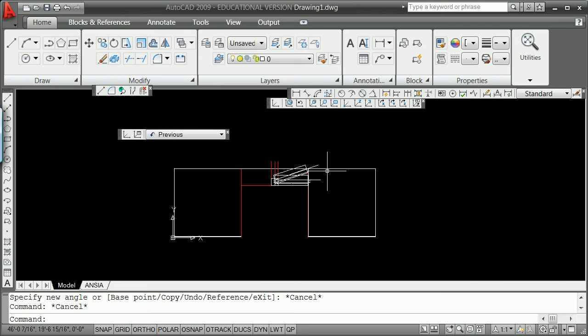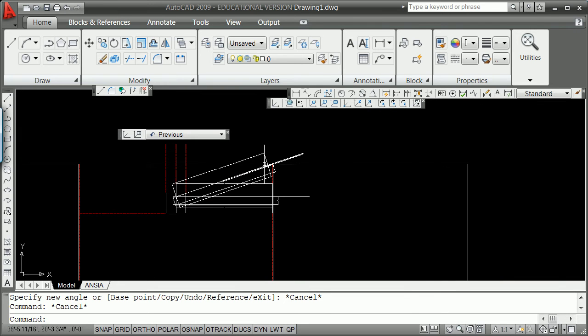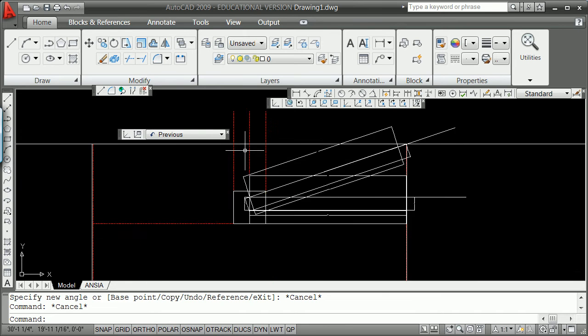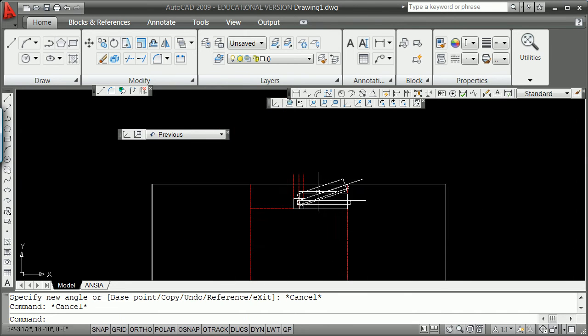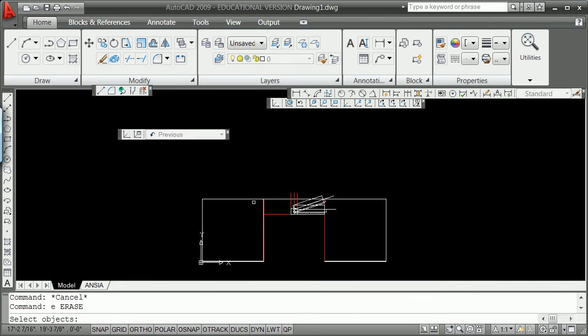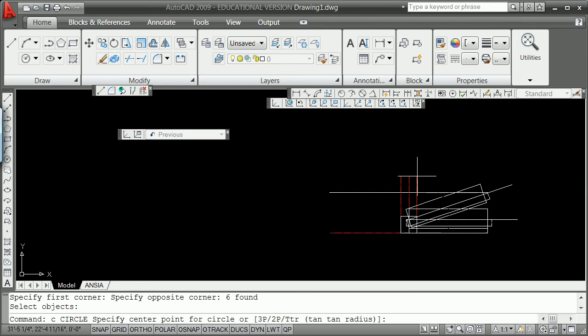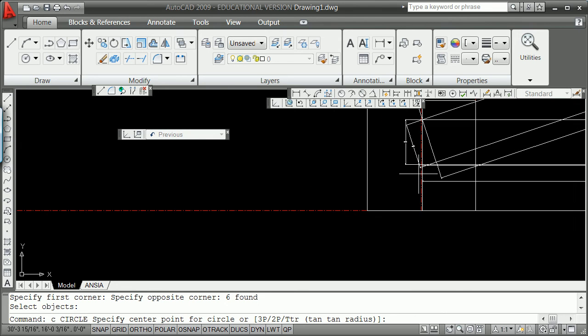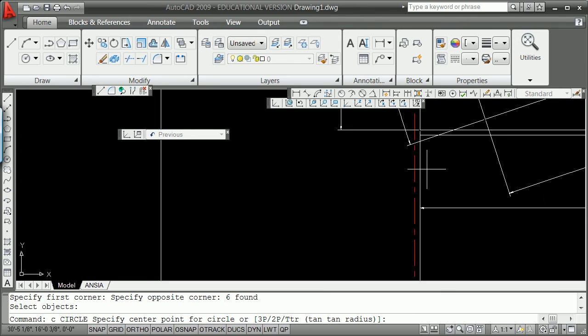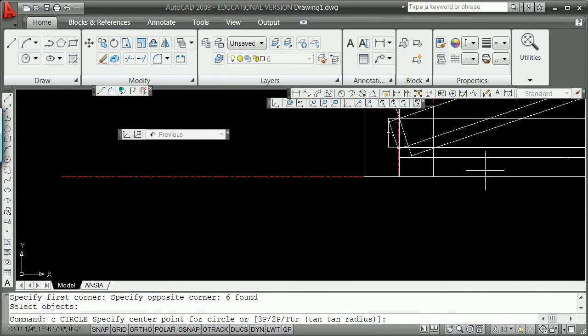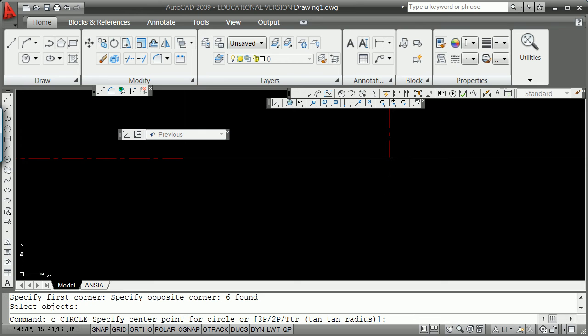We can go ahead and save this. So when we're saving, what we've got is really 2 blocks and then some geometry if you want to steal it and bring it back. And more importantly, the dimensions. So I'm going to go ahead and get rid of this. Get rid of that. Clean everything out. You might not want to get rid of it. You might want to right block it. Kind of getting all of your... And in all reality, it probably wouldn't be a bad idea now to move this entire thing so that logical point, which is down here, that 0, 0 is at 0, 0.